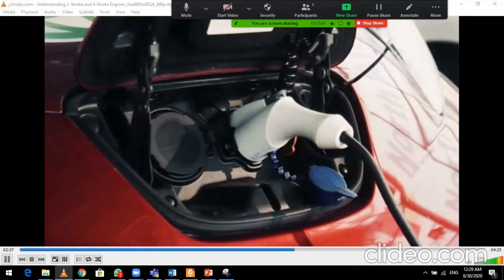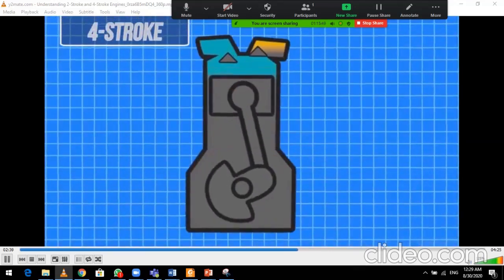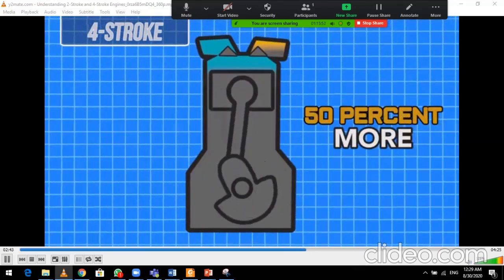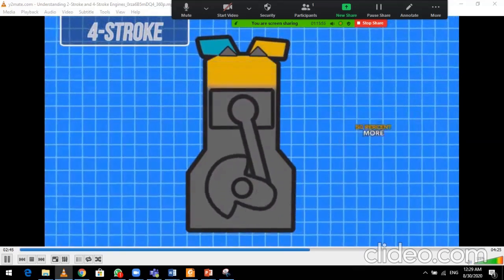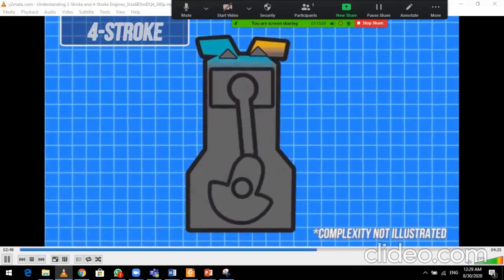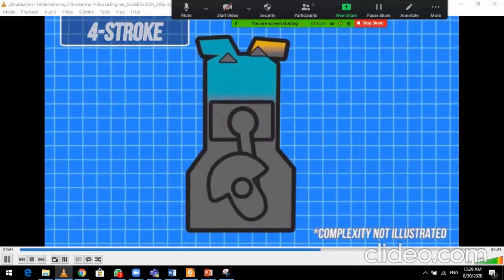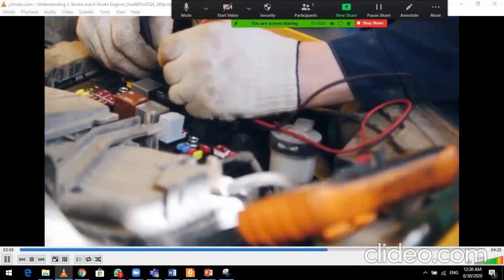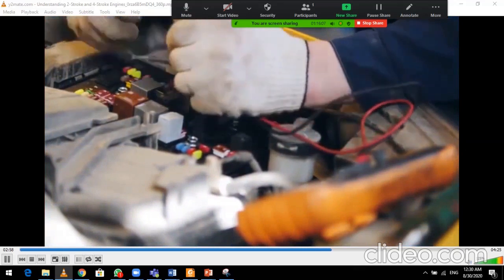Efficiency isn't everything, though. A 4-stroke is certainly more efficient, but they also weigh upwards of 50% more than a comparable 2-stroke engine. This weight is due to more complexity within the motor's mechanism, which also leads to significantly more moving parts in a 4-cycle engine. In terms of simpleness and easiness to fix, a 2-stroke engine easily wins out.